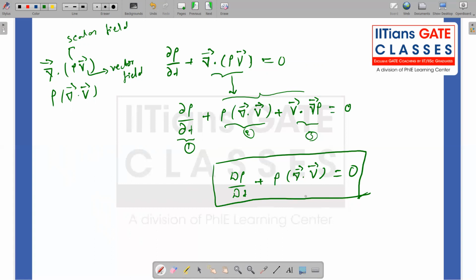And a very famous equation. People usually check the incompressibility of the flow field by using the divergence of the velocity vector to be zero. If the divergence of the velocity vector is zero, they say that the flow field is incompressible because the density is constant.